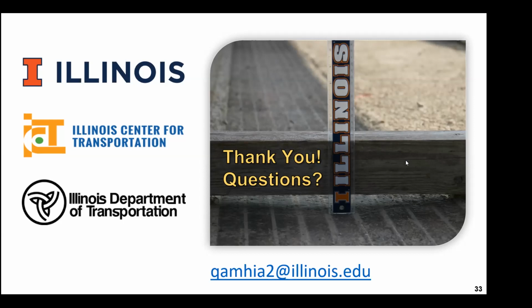Right. Actually, I will answer your question, but this reminds me of a point that I probably forgot to mention during the presentation. When we tested the lab samples versus the field samples, what was different is the amount of curing that you had in the samples. So in such a test setup, if you test just lab samples that are cured for 7 days, and then you want to get the performance for long-term, 20 years in the field, then you might be basing your testing on misleading results, because you're omitting all the curing that will happen in the field and the long-term effect of the curing.